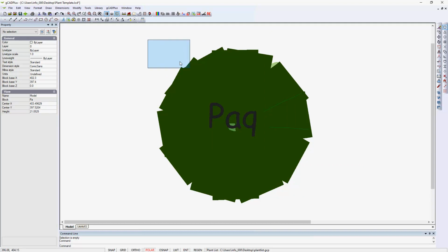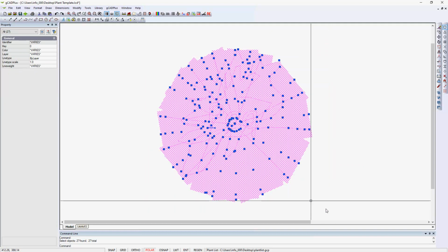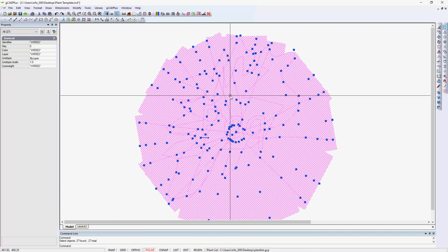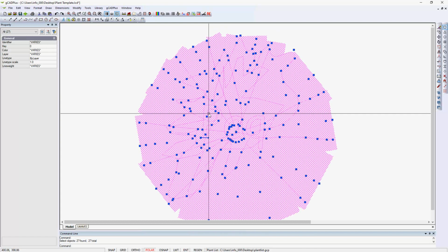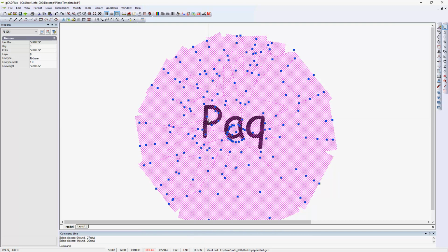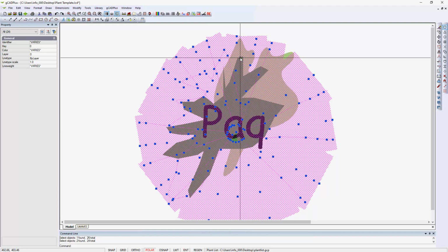How do you fix it? Well, let's grab this. So I've grabbed all of the symbology there, making up the symbol. I should be able to select, if I hold the shift key down, I can take out that piece of text. There's an interesting series of polylines with some fill going on behind them. So I now have a selection set.